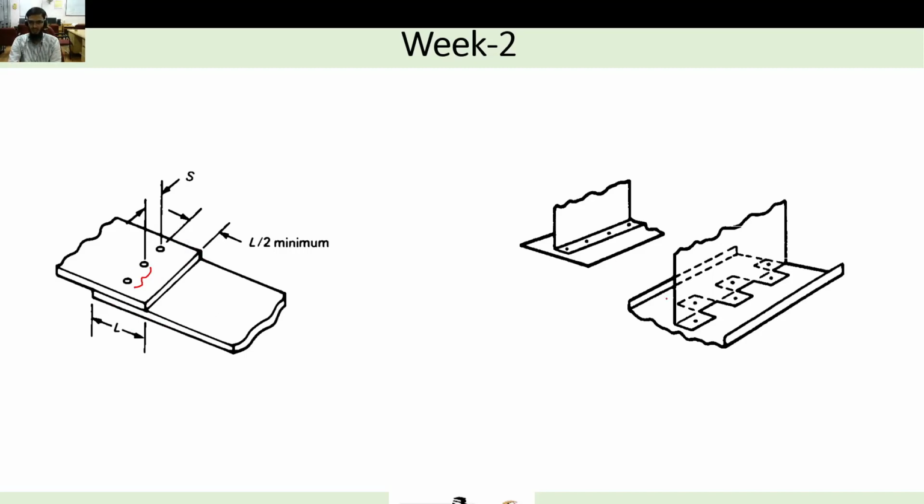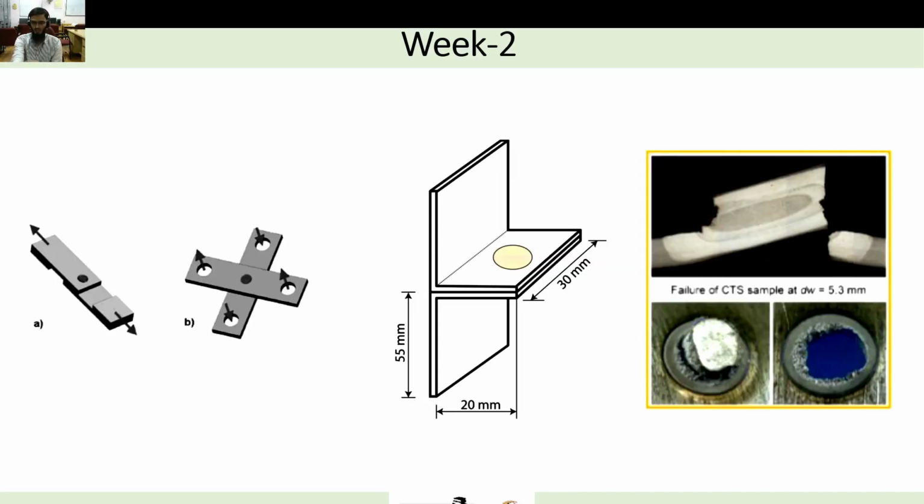This is the lab configuration which you can see here. Coming to the design, you can see continuously you are welding at one side only, and on the other side there is no weld. This will lead to stress concentration at one side, while the other side is totally free, so it will be damaged or fail during service. The better design is, instead of continuous welds at one side, to use a staggered one in a zigzag configuration. Weld here first, then here, then come to here, so that on both sides the forces will be balanced in the actual application.